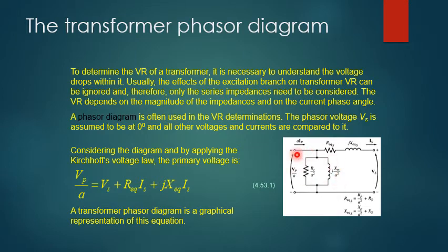So what we can see is that this is an equivalent circuit of a transformer, and in this equivalent circuit we can ignore the excitation branch losses because they are very small, so they can be conveniently ignored. So we actually have the series resistance and the inductance to consider. The series impedance is to be considered while calculating the voltage drop across a transformer.